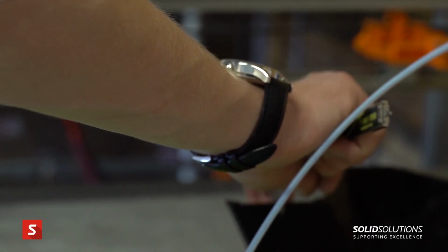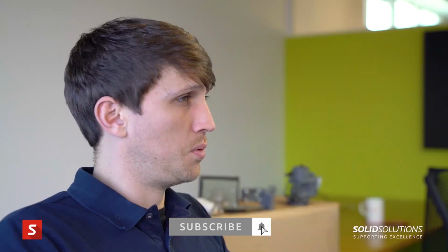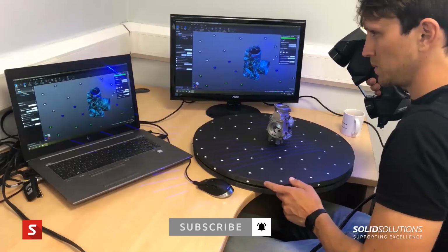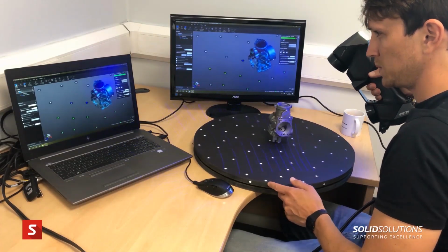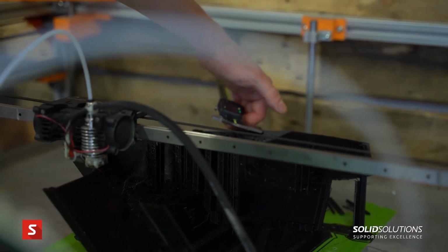Generally speaking, reverse engineering refers to the process of copying an existing product for the purpose of remanufacture. There's a lot of different ways to do this, from manual measuring techniques to more advanced methods using CMMs and 3D scanning. For many of our customers, the process of reverse engineering will typically involve them taking a real-life object and measuring it with either a tape measure or a set of calipers, and then using that information to create a SolidWorks model. However, some of the customers are now beginning to use 3D scanning to help with this process.